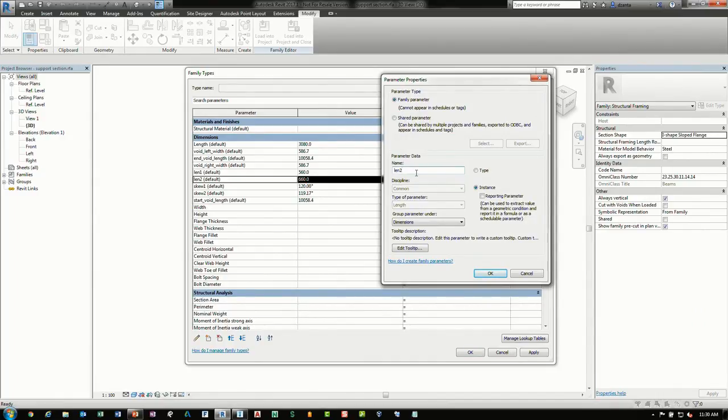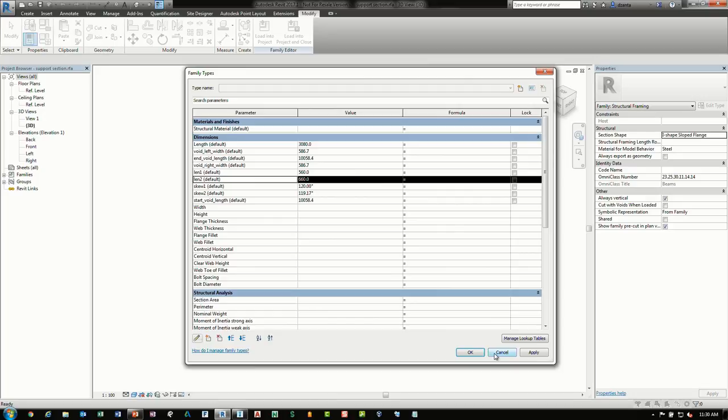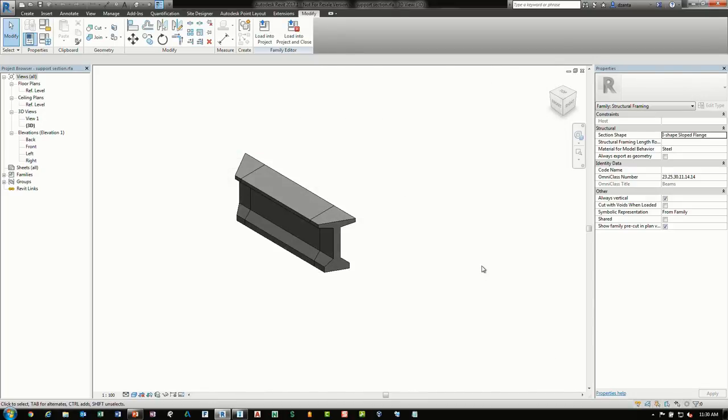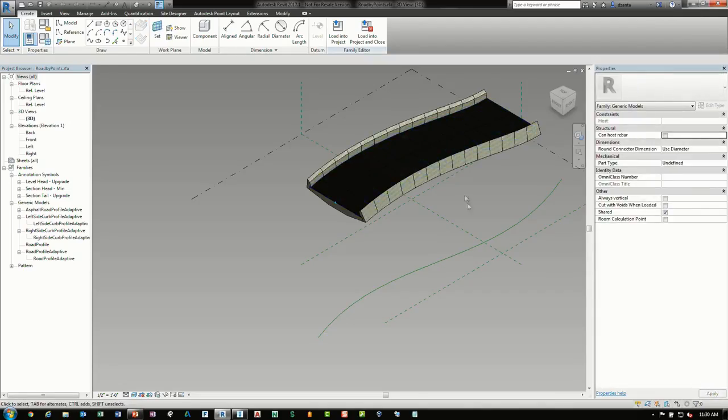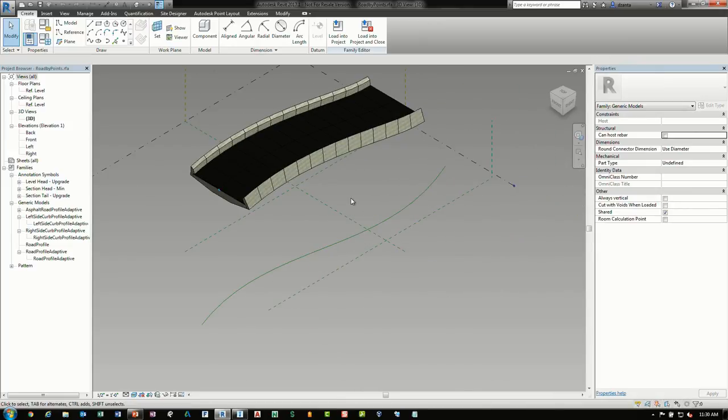Yes. Okay. What you're going to notice using this workflow and looking at the InfraWorks bridge that goes out of InfraWorks into Revit is that some of the families are very intelligent, like you're seeing here. Some are not so intelligent. Okay. When we take a look at, lastly, a few other families, let's see, that's the abutment, same as the other one. Let's switch over to, let's do this one, road by points. All right, so when we take a look at how do we use Revit as an example, to create the bridge, say, from scratch.